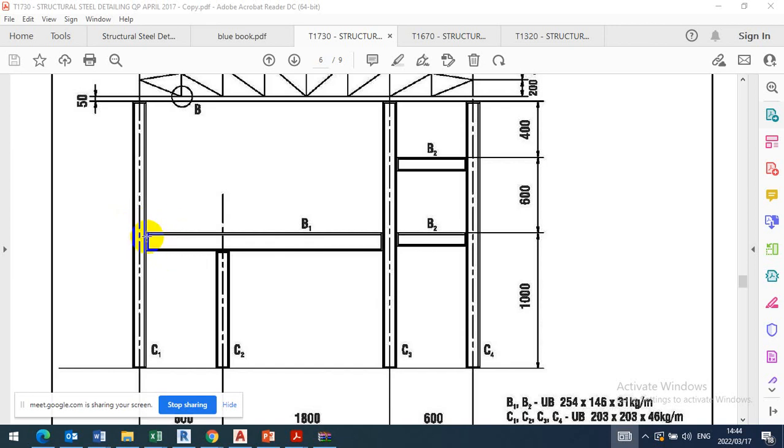You get some other questions where the beam is connecting into the web inside here. Maybe it's turned the other way. But the way we look at these ones, where you see the dark portions, these are the flanges of the H-sectional columns. So this beam has its I section connecting on the face of the flange of this column using the end plate. And that end plate comes already welded on beam 1.